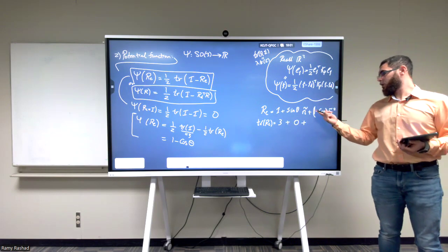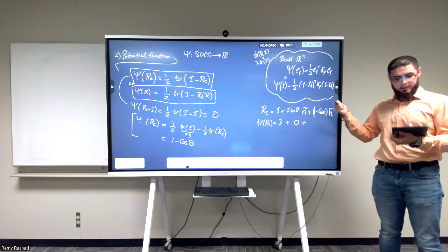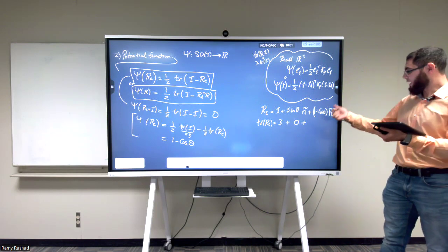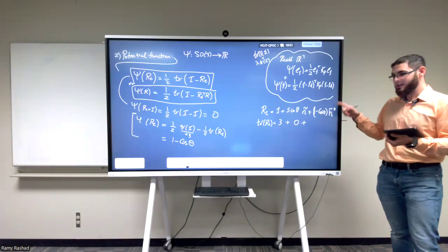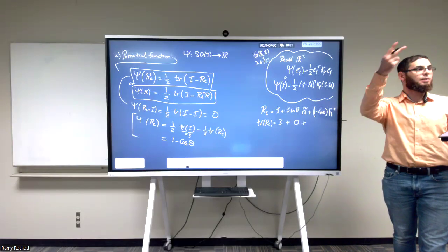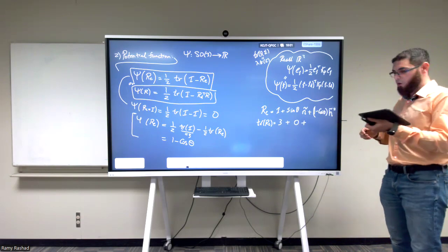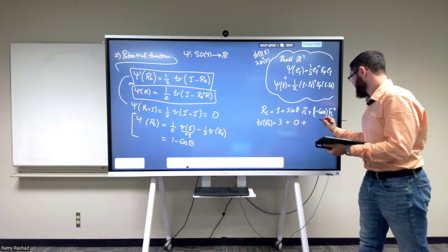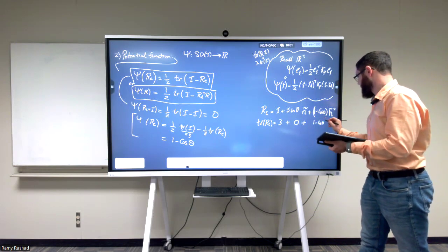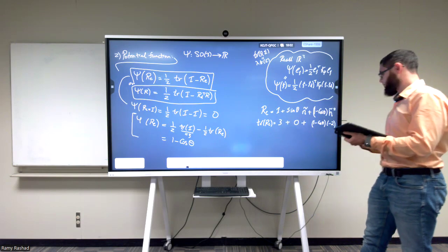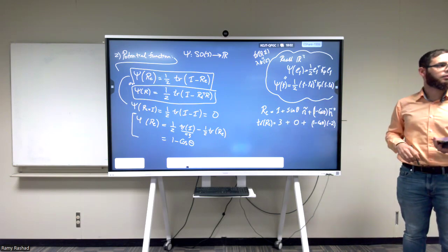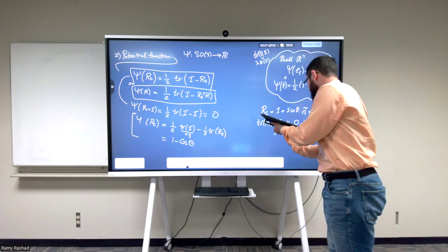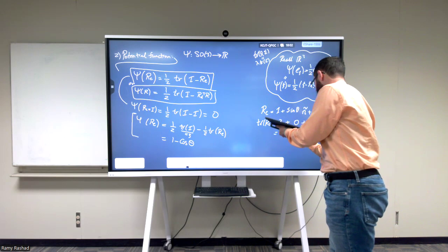Then I have the same here. So I have 1 minus cosine theta multiplied by the trace of this term. It's very easy to prove for yourself that the trace of any skew-symmetric matrix multiplied by itself, so squared, will be equal to -2. So this is 1 minus cosine theta multiplied by -2. You can show it for yourself. So in the end, the trace of R can be written as 1 plus 2 cosine theta.